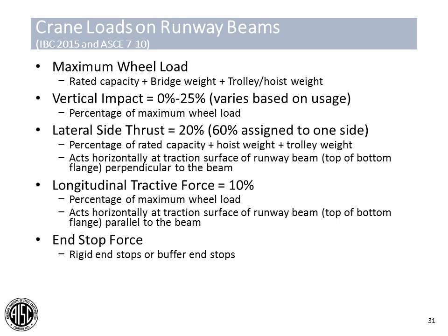What is your position on the fact that runway beam deflection is limited to L/450, while buildings are limited to L/250 or L/300? How does the building deflection relate to the crane beam deflection? You really need to consider the entire runway and building, the portions of the building that are supporting the runway, as a combined system.